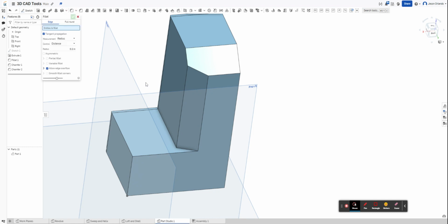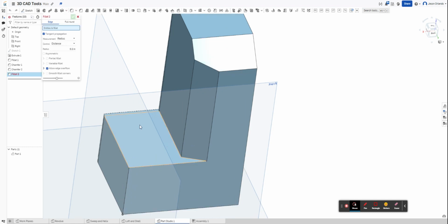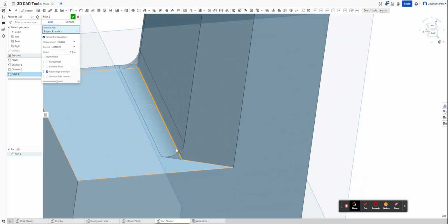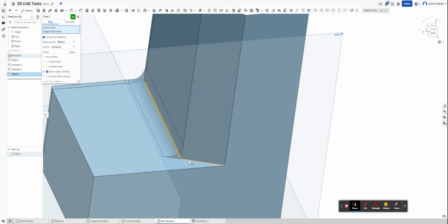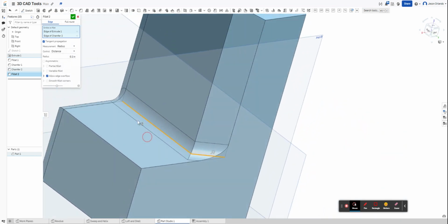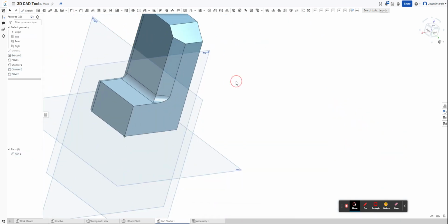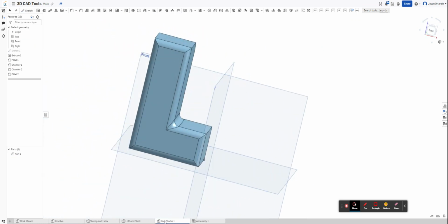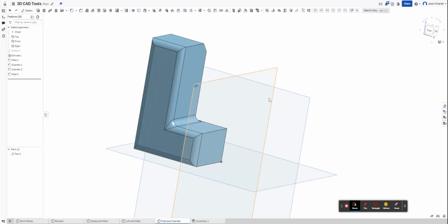And let's go back, use the fillet tool maybe on the interior corners. I could fillet along an interior edge, and in that case, it fills in and rounds, kind of adds material to round that in. Might go around and just, yep, there you go. Kind of get some fillets to transition that inside. And so there you go, some edge treatments, fillet and chamfer. So I'm going to rename this Part Studio Fillet and Chamfer. Just make sure you've seen those and can use those as well.